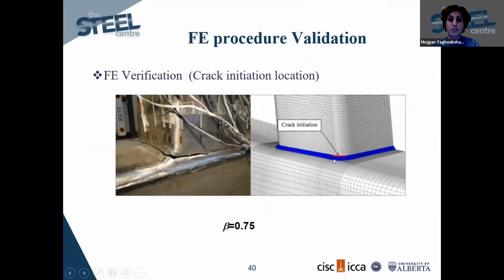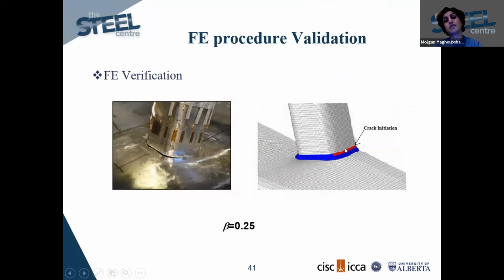The finite element solution was also able to predict the crack initiation. These red elements mean that the fracture actually happens in this portion, so these elements don't carry load anymore.